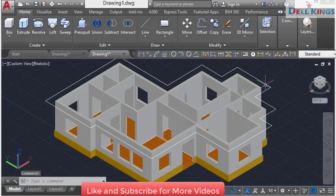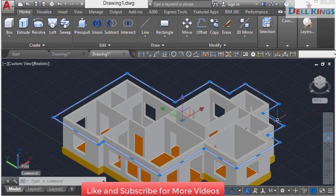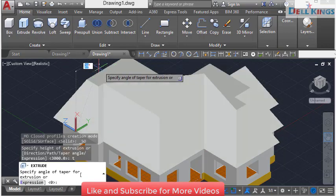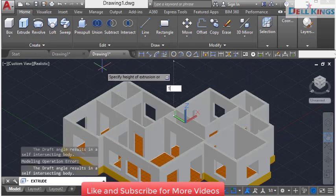Now press enter. So now we're going to extrude this for the roof. Just select this pan and select this line. So you can now select extrude from here and type T for taper and press enter. So we now select an angle of 45 degrees, press enter. Now go up by 1000 millimeters and press enter.